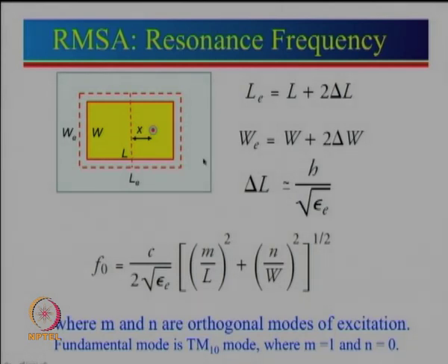Now, the voltage distribution will be the reverse of that. Open circuit means the voltage will be maximum, then it will go to 0, and then come back to minus. So plus, 0, minus. Again this is nothing but a length equal to lambda by 2, which is a variation of the waveform. Since voltage is maximum here, the current is close to 0. Here it will not be exactly 0, but we only see the physical dimension. Nevertheless, the current is small and the voltage is maximum.